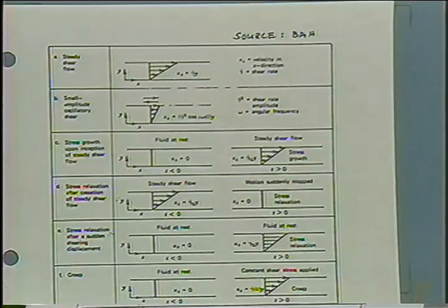The kinematics used in those shear experiments can be variable. We can have all kinds of time-dependent experiments performed. We can have a steady shear rate, or we can have oscillation or step strain put in. So we can have shear deformations of all kinds of time dependence and measure material functions accordingly.